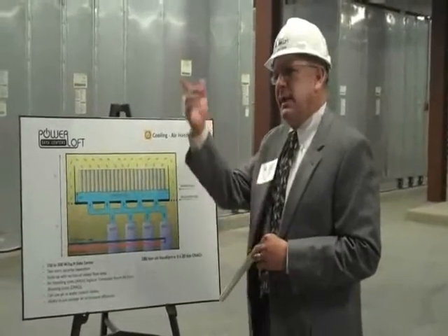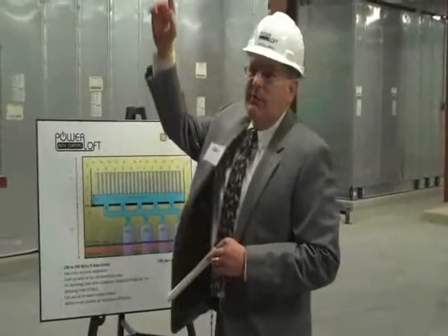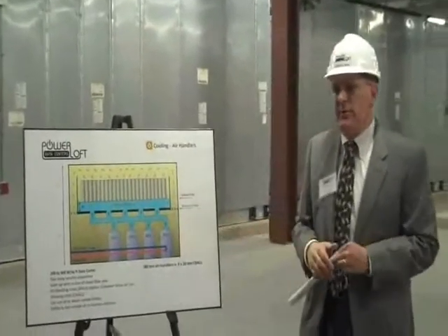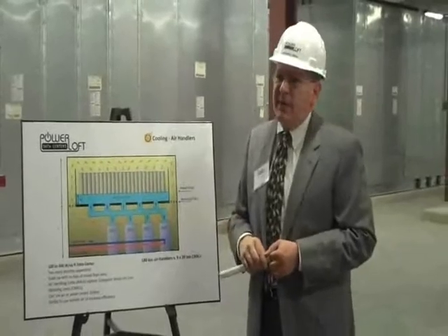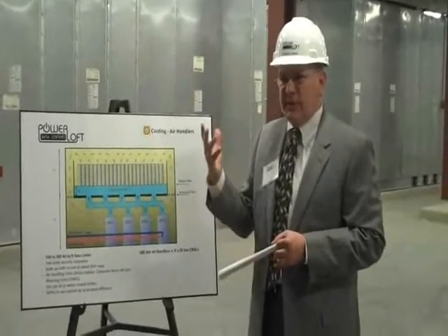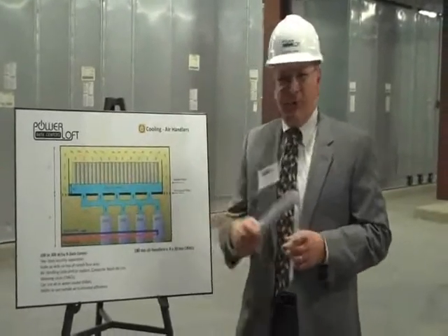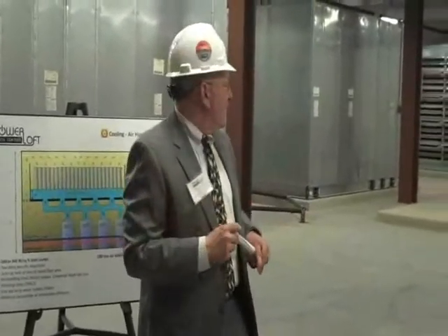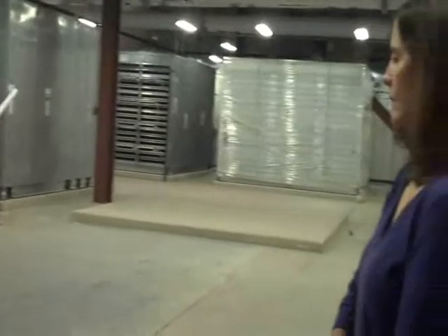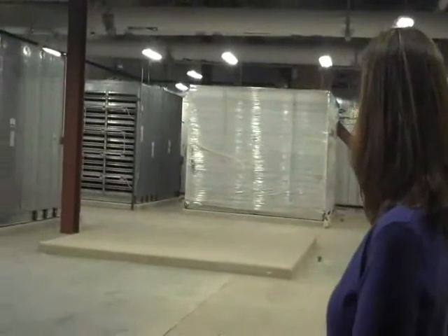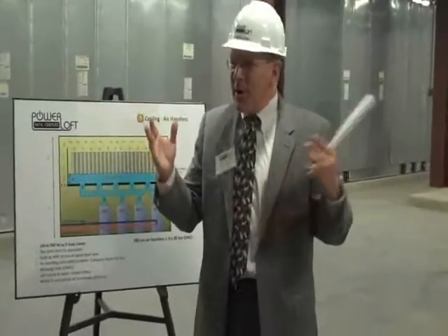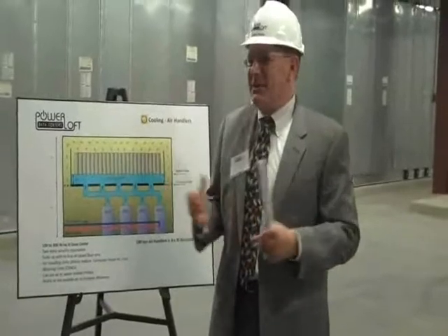If you notice on the outside of the building, the louvers, we have the higher and the lower louvers. The lower louvers, we can actually bring in free cooling, cool air in the colder weather. We have to humidify it because the servers and the racks are very sensitive. In fact, the last tour that was in here got very loud. The compressors came on, the humidity control came on. There's copper piping along the wall, and it has little heads on it, little nozzles. It's like if you've ever been to Disney World when it's really hot, they spray on you. Well, you walk in here and it's a mist. It starts to feel like a spa in here.